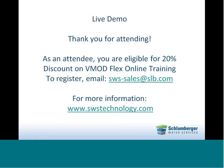Another question, which tutorial to start out with if one is using VMODFLEX for the first time? I think it depends on what your modeling approach is. If you have a set of numerical model files and you just want to see how they look and feel in VMODFLEX, then you want to follow the numerical model tutorial. If you're building a brand new flow model, you can follow the conceptual approach because then you can have all the benefits of assessing various grid approaches and whatnot. And the conceptual model is laid out in a very easy-to-use workflow approach as well.